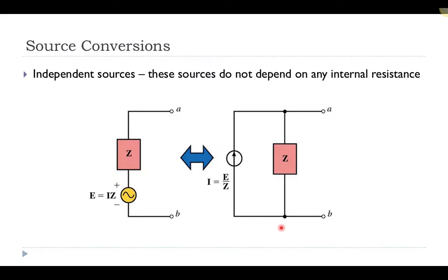So in the same regard, it was sometimes necessary to have a source that was a voltage source in DC converted into a current in DC. And so a real voltage supply always consisted of the voltage supply in series with a resistor. So here a real voltage supply consists of a voltage supply in series with an impedance, and it is equivalent to an AC current supply in parallel with the same impedance.